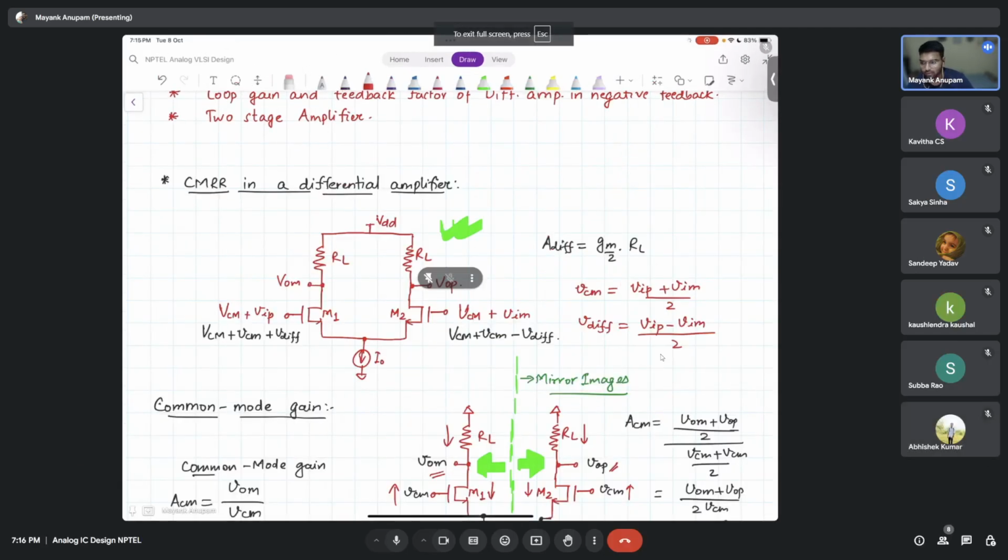Yeah. So I was saying that the same amount of small signal current is going to flow through both of these, right? So now, if VCM is rising, you expect the current here to be rising, right? But the current will be rising in both of them equally, right? The current should increase in both of them equally. Is that correct? Yes, you are correct.